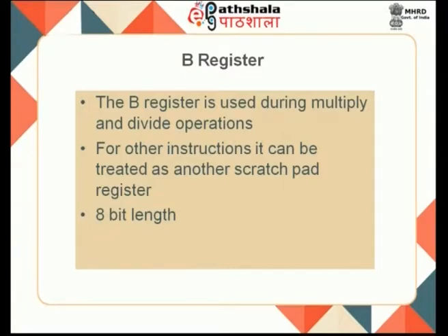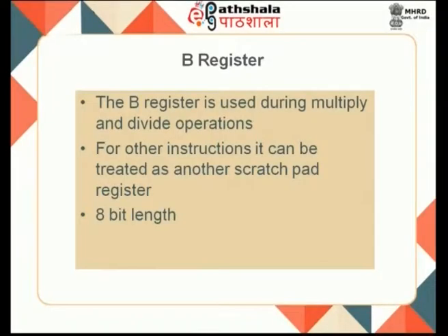Now the B register is also a very important register for your processing. Usually in arithmetic, for multiplication and division operations, one of the data will be stored in the B register, and otherwise it can be treated as another scratch pad. It is similar to the A register, and it is also used as a scratch pad register. This is also 8-bit length, as the 8051 is an 8-bit processor, so all the registers are of 8-bit length.